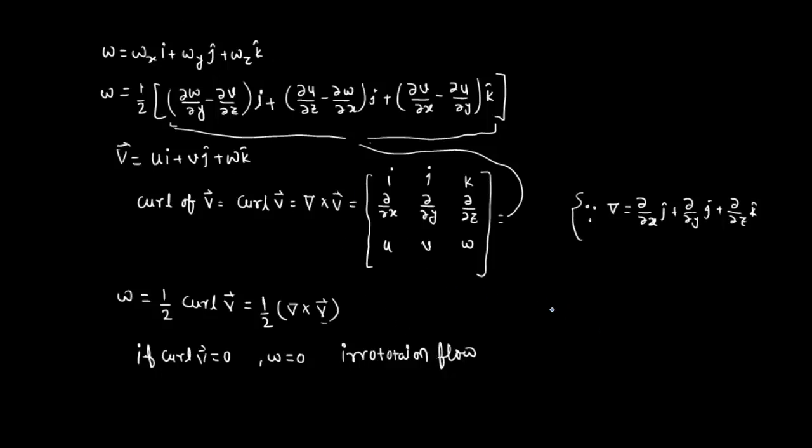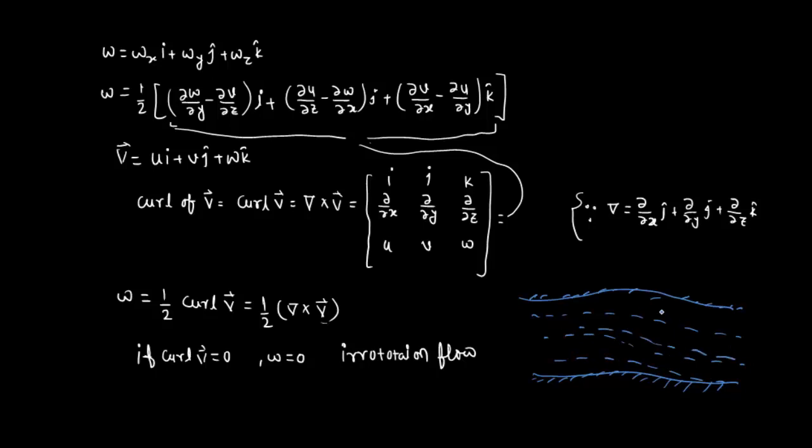Now here we can understand some more about the rotation. Let's suppose we are considering a river here. Let's suppose this is the river bank, and water is flowing over here. If we draw the velocity distribution, we are taking this as the cross section of this river. Obviously from the no slip condition at these river banks, the velocity will be 0 and the distribution will be parabolic, and it will look like this one. This is the velocity distribution of this field, the velocity vector field.